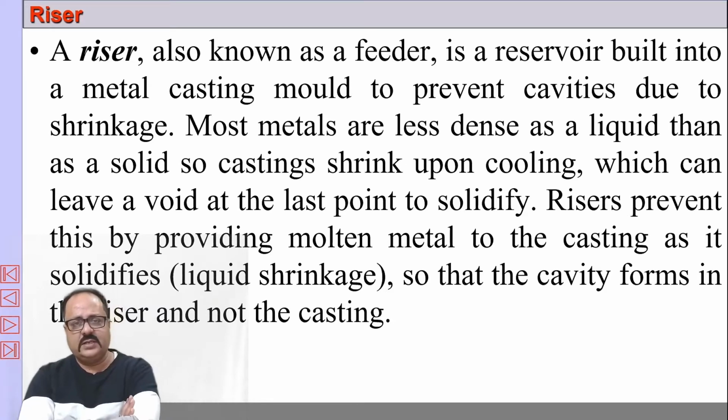In this lecture, we'll be discussing riser design. Before we start discussing what riser design is and its aspects, we should know what a riser is. A riser, which is also known as a feeder, is basically a reservoir, a cavity built in the mold, which stores molten metal and supplies it when there is liquid shrinkage of the molten metal in the mold cavity.